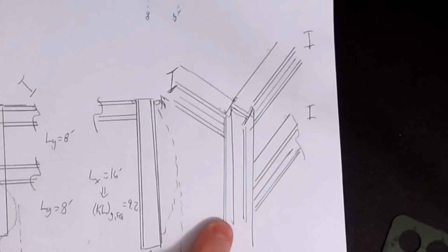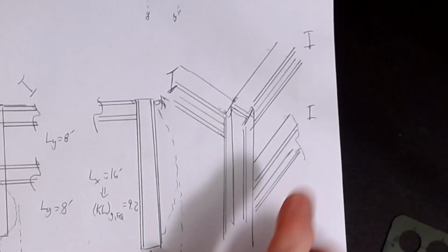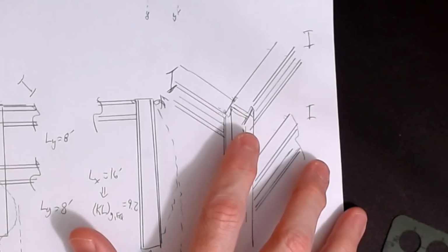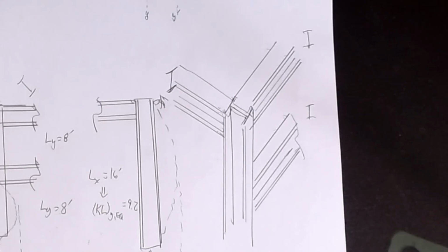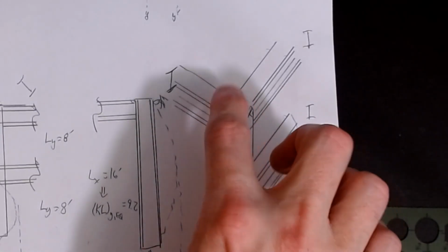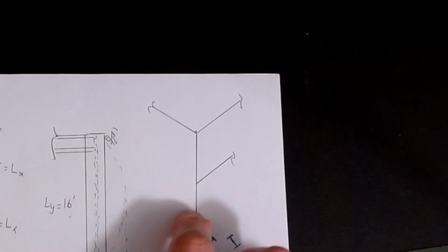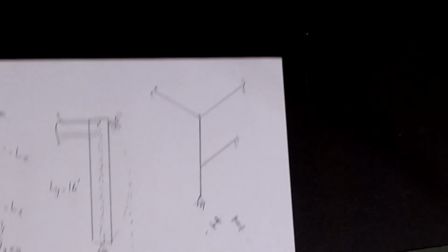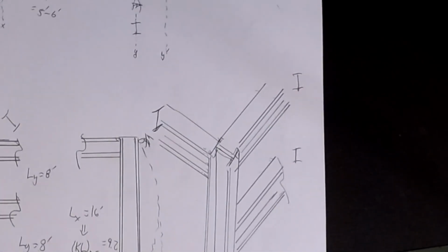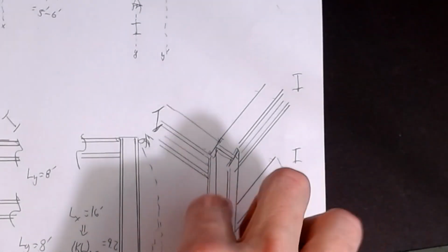Okay, this leads us to another conversation. If you're using any sort of software, such as STAAD or RISA or ETABS, RAM Steel, whatever the case may be, any sort of steel design software, lots of times we put our models into the program so that it looks something like this. Well, the strength of the building and the deflections and the performance of the building are dictated by the orientation of the members. You got to make sure you get that member put in right.